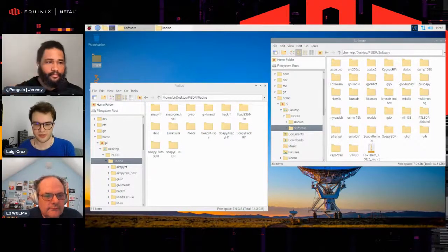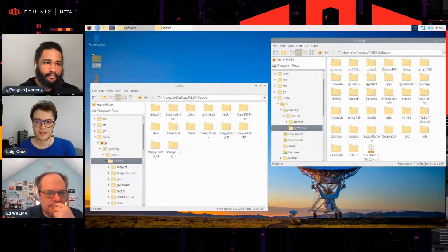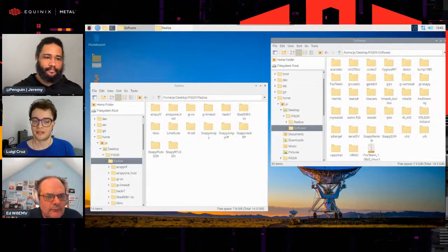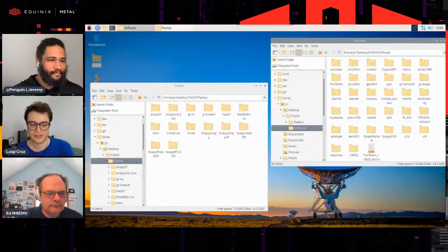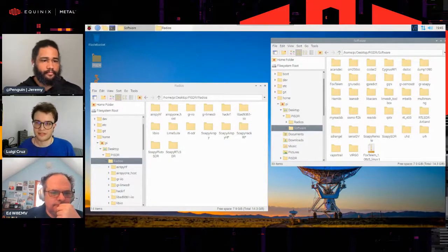So I wrote the original open source demodulator that is used to demodulate the NOAA 20. It took a lot of work to do because almost all satellites use a protocol called CCSDS, a committee for space data systems that tries to make a common standard for all the data links. So the NOAA 20 used this data link, the CCSDS, and my friend Lucas Teskey and I started this project called Open Satellite Project that aims to decode lower orbit satellites, and like the GOES, that is a geostationary satellite.